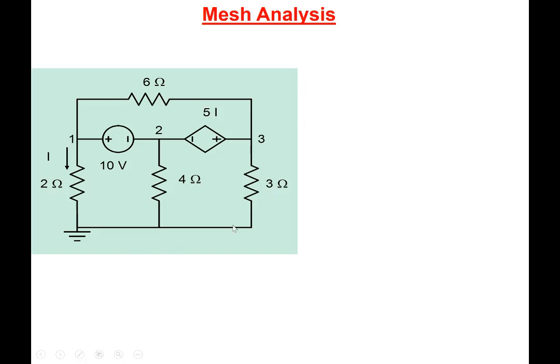So this is the circuit that we will analyze, and the circuit has one independent source here, a voltage source, and this is also a dependent voltage source which depends on this current I here. So first thing we'll do is analyze the circuit, obtaining voltages and currents using mesh analysis. So we identify the meshes. There's a mesh here. We identify a current here. We identify another mesh here, and another mesh here, right? Three meshes. We assign them currents I1, I2, I3.